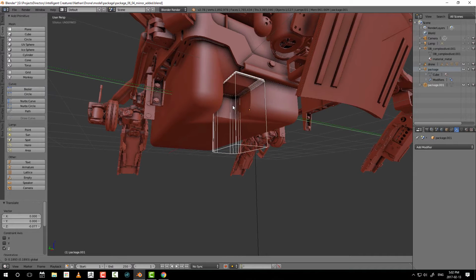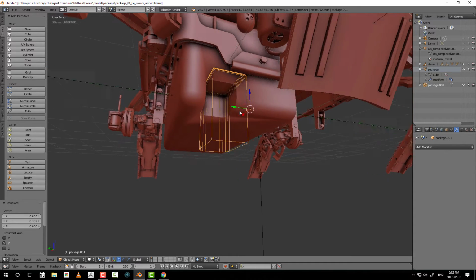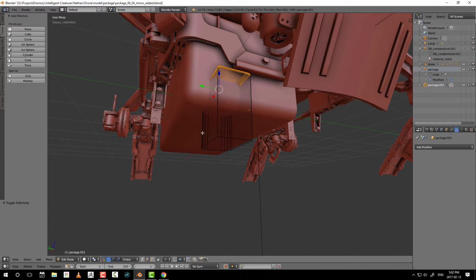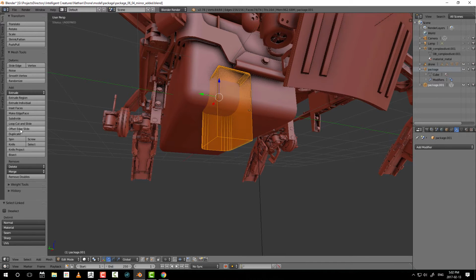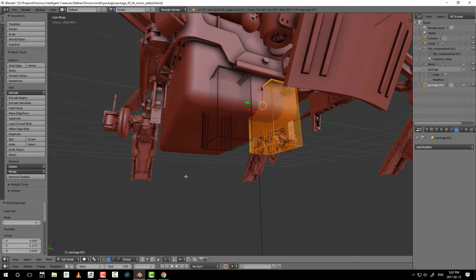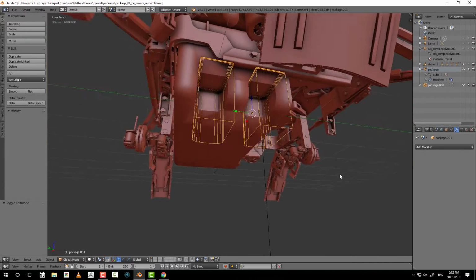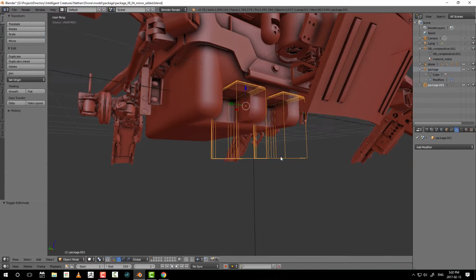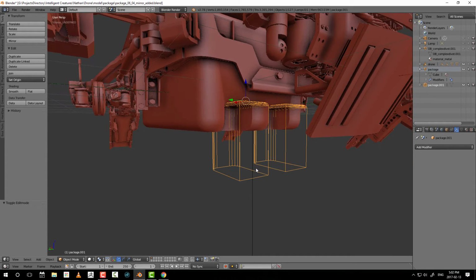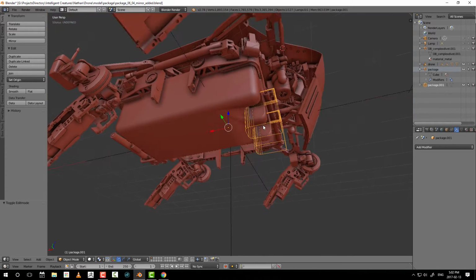But the cooler thing about this tool is the fact that now, if I press edit, right, and then let's just say I hover over a part of it, and then I do a tool duplicate, and I constrain to Y in my case, okay, and then I tab out, you'll notice that now, even if I change the object itself, it's still linked to this shape, right? So what I just did is I duplicated polygons, but I didn't actually duplicate the object. Now, that's the difference, right?